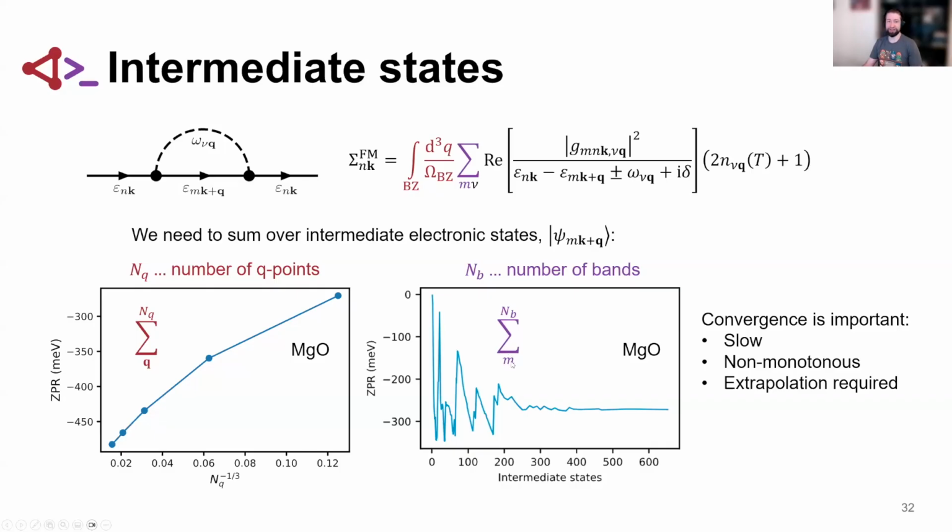And that is why, on the previous slide, the default is to set ELF-nbands to -2. So it just uses all the bands available in order to increase the chances that this converges. If it doesn't converge and you look at this kind of behavior and you still see wiggles at the end, then what you have to do essentially is to redo the calculation with a higher ENCUT, so higher electronic cutoff energy, so you can generate more bands. But with a meaningful default ENCUT, so a bit higher, usually this already converges with the pseudopotentials that we provide with VASP. All right.